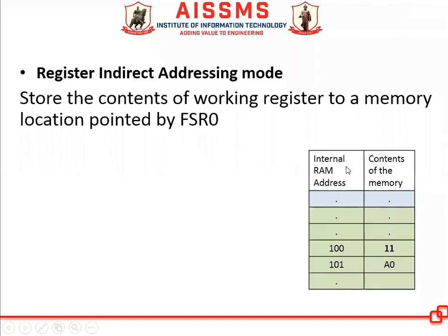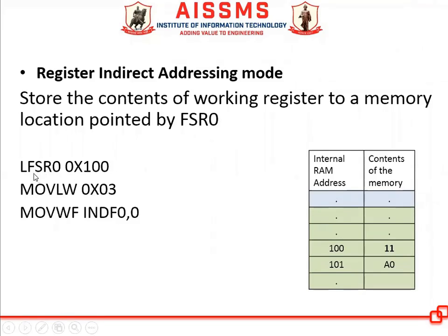This is an internal RAM which is shown. We'll be loading FSR 0 with an internal RAM address, say 100, using the instruction LFSR 0, 0x100.